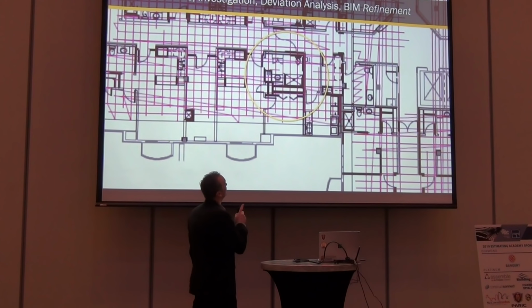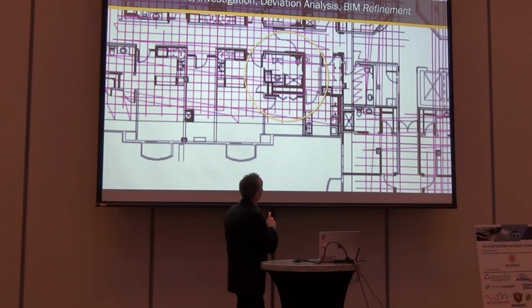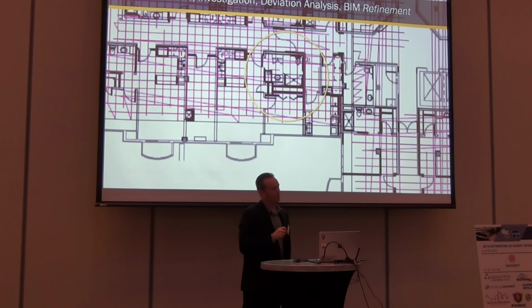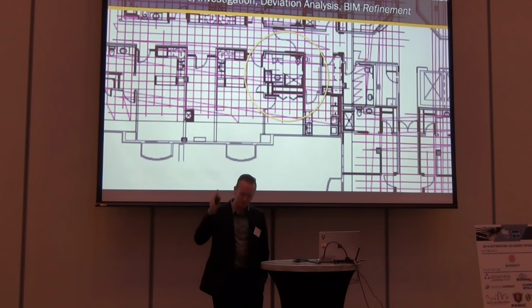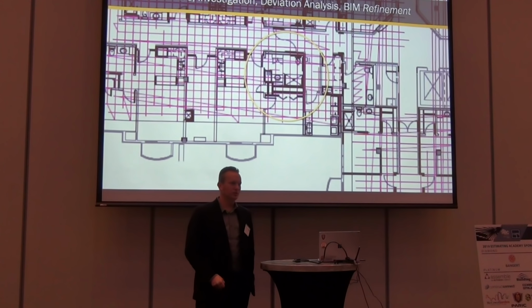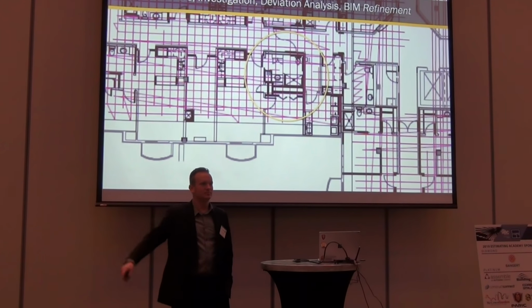So what we did was we went out, started to do a little demo, started to understand where things were, the repositioning of this project. Everywhere that we wanted to put penetration in the slab was perfectly on top of the PT cable. And the way that we knew that was we x-rayed the entire slab.